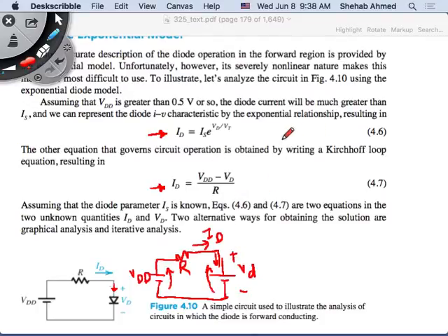No. 4.6 is what we talked about five minutes ago. Yesterday, we talked about the forward characteristic of the diode. It was IS e to the V diode over VT, -1. We said that if I'm only operating in the forward characteristic, then if the voltage is negative, e to the minus x goes to 0, and I get I equal to minus IS.